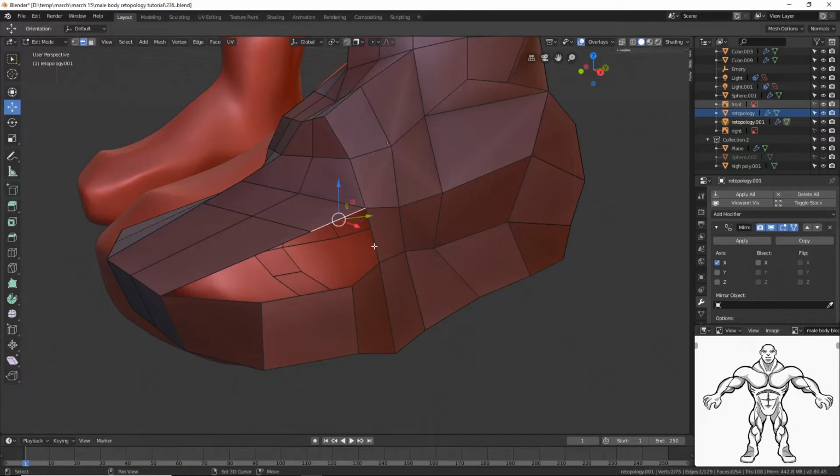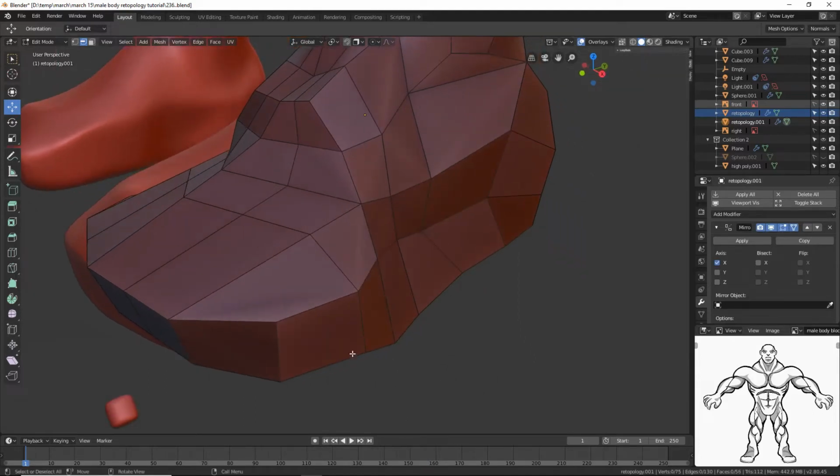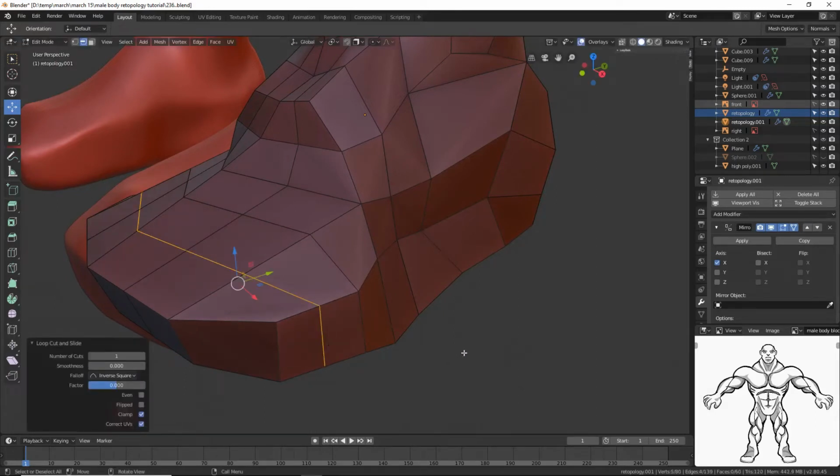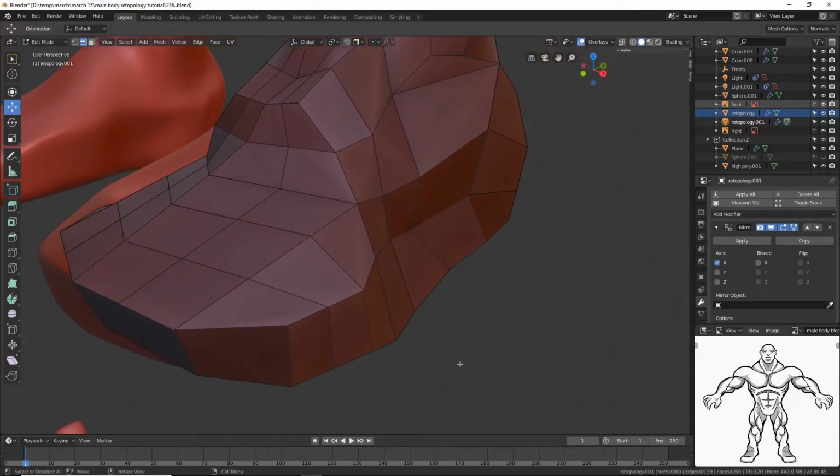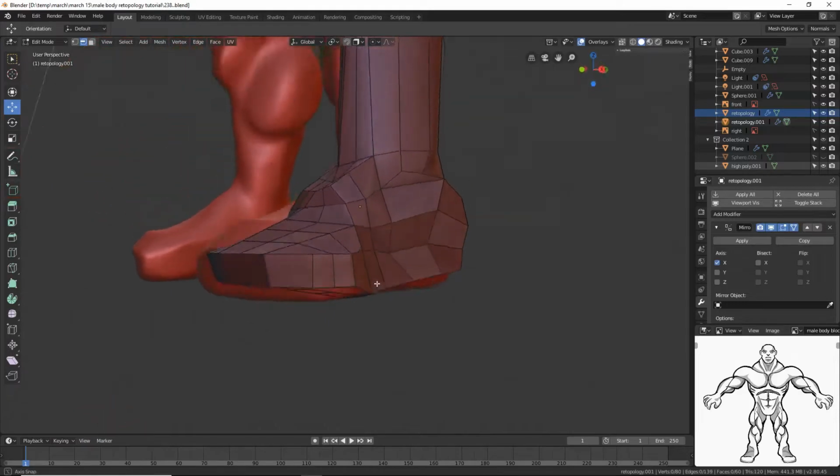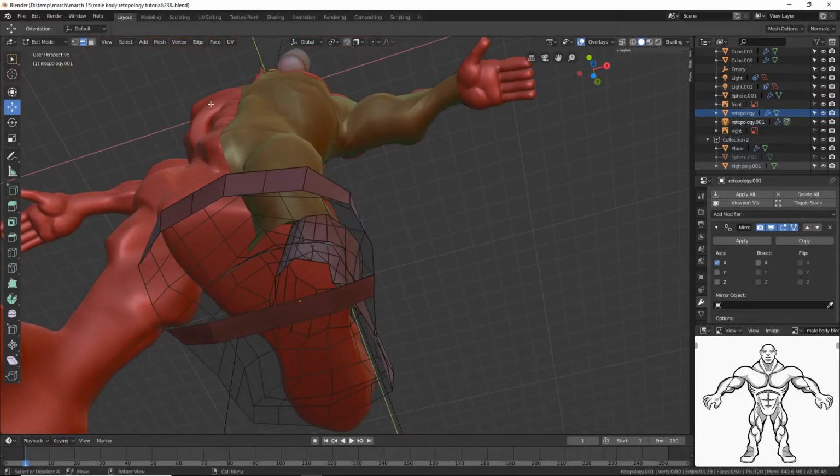Okay, I'm going to left click here, hold Shift, then press F to fill. Left click to deselect. I'm going to click here, hold Shift, then press F to fill. I'm then going to left click here to deselect. I'm going to hover here, hold Control, press R, left click a second time to lock that in. Left click a second time, then, to lock that in. Okay, what I'm going to do is hold Control and the middle mouse button to zoom back. I go to vertex select, hold Alt, click on that edge. I can see this is 9 verts right here.